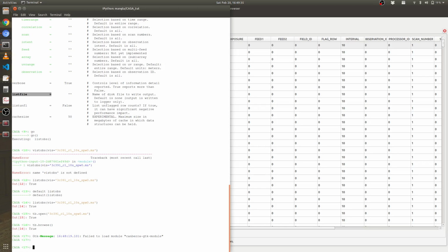If there are two antennas, there's only one baseline. A baseline is when you do the correlation. So how many correlations can you have? Two antennas is one baseline. Three antennas is like taking points A, B, and C. So AB is one baseline, AC is one baseline, and BC is one baseline. So there are 3 baselines.